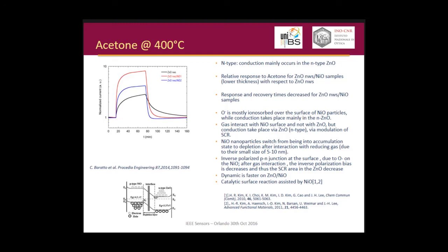But we observe that there is an optimum thickness for this, and this effect is probably due to the interaction of one of the materials, which is nickel oxide, with the gas, while the conduction takes place through the zinc oxide nanowires.